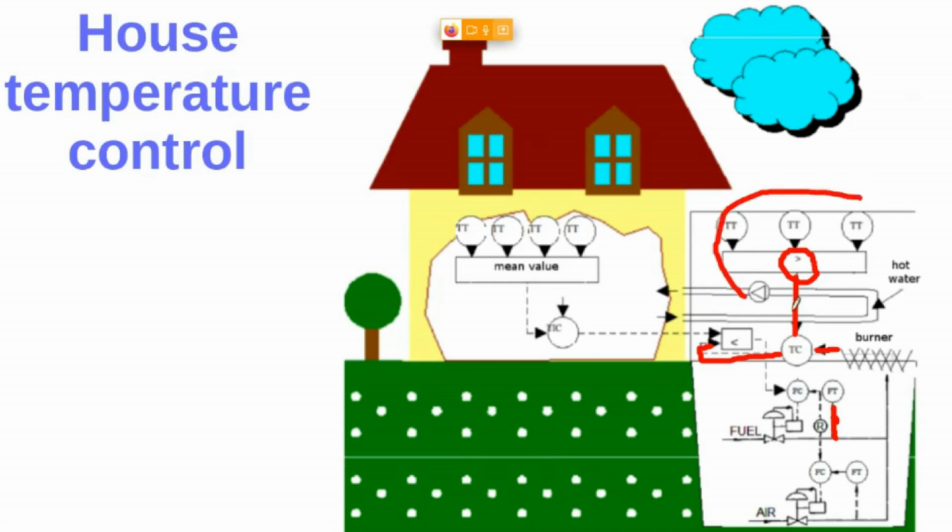So this is a selection, but this will be an override because at the end, we are applying the selection on several controller actions, right? Manipulated variables, because this is also a manipulated variable. Here we have the temperature controller. Remember that here we have an I in the middle.